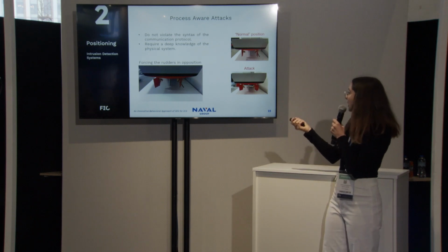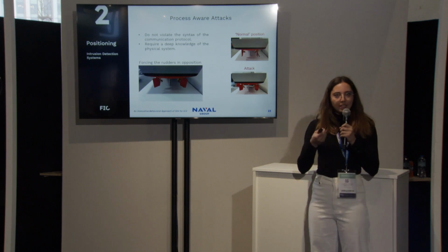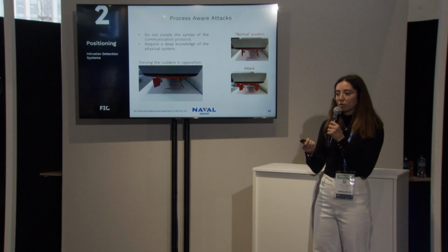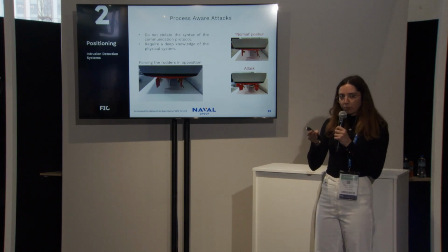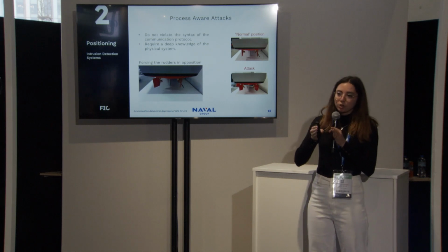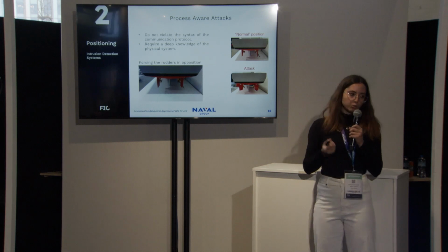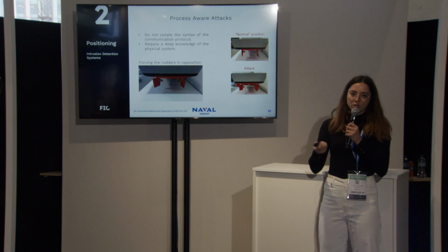This would be an attack. And to do that, the command that you send is totally legit. In terms of the syntax of the communication protocol, it is allowed to move the rudder. The problem is the synchronization between the two rudders. So you would not detect any violation in the communication protocol. This is what we call a process-aware attack, and it is the thing we are interested in.